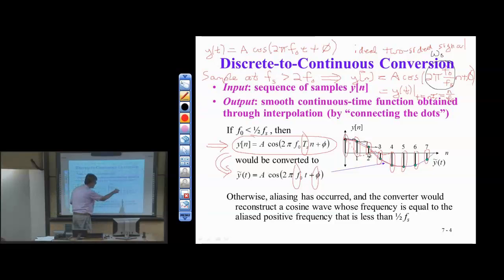Okay, so again, this has to be a two-sided sinc. And a couple things you'll notice is the sinc that we would need is a sinc pulse in the time domain. What's the Fourier transform of that? It's a rectangular pulse, or a rectangular shape. It's an ideal low-pass filter. Okay, so think back to when we talked about sampling. If I'm going to sample a signal, and I obey the sampling theorem, again, this is all idealisms, then how do I reconstruct? I apply a low-pass filter.